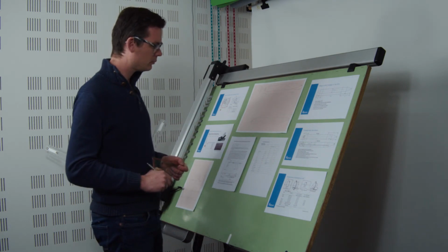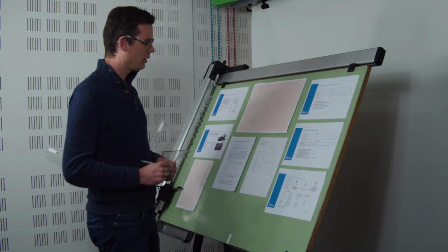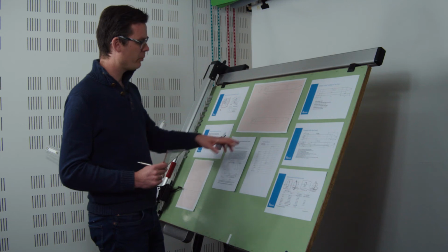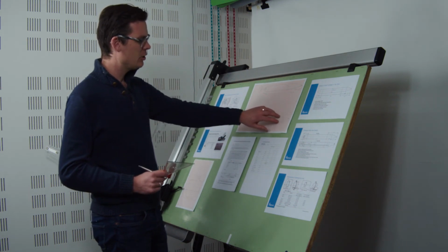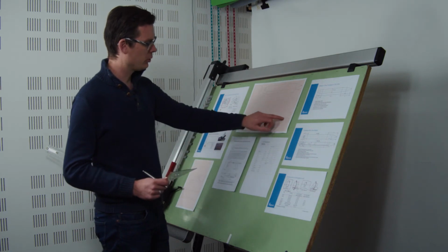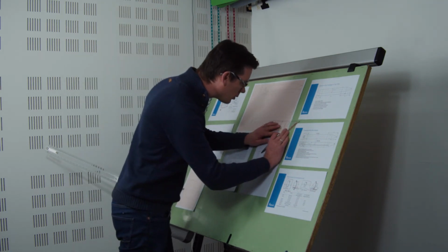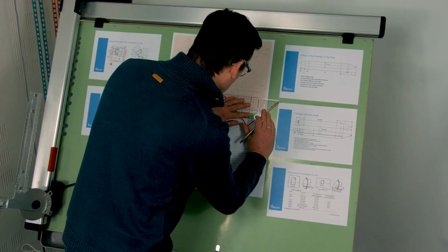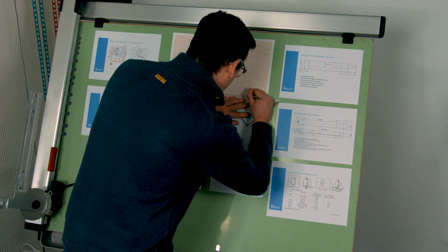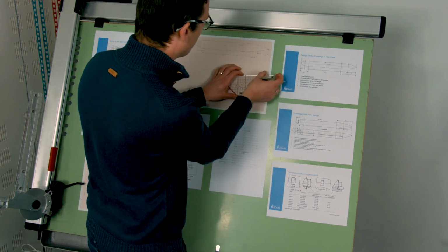Yeah. So a galley is typically about 90 centimeters in width. So if I want to position my doors, I need to be 90 centimeters away from the aft pressure bulkhead that is located over here. So I'm going to go 9 millimeters on my drawing, making a starting point for my type 1 exit over there.